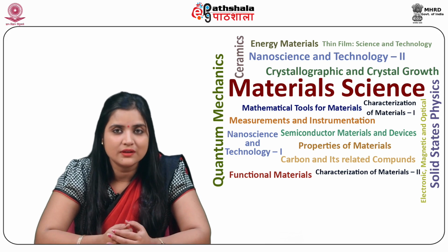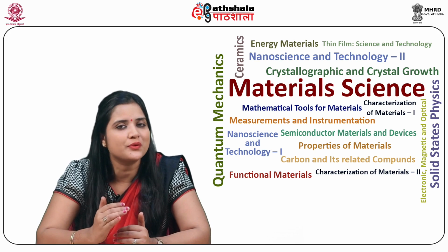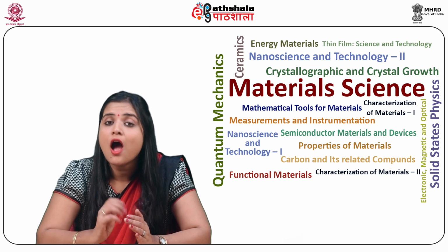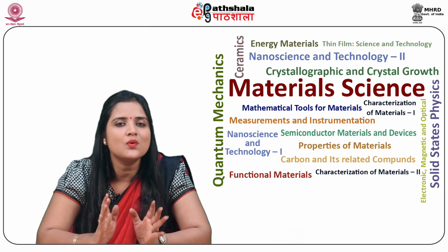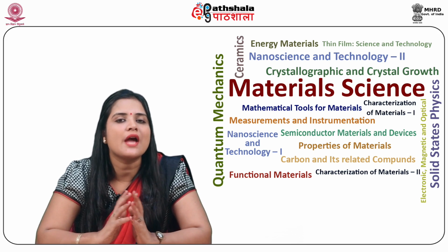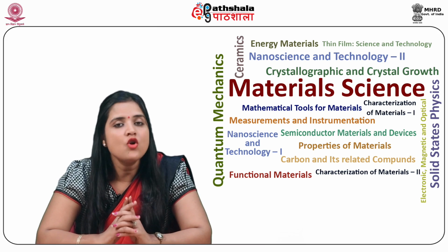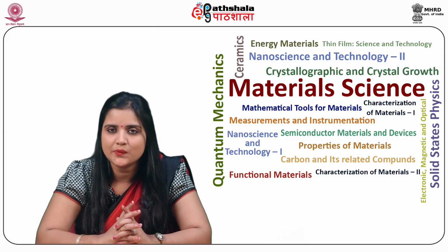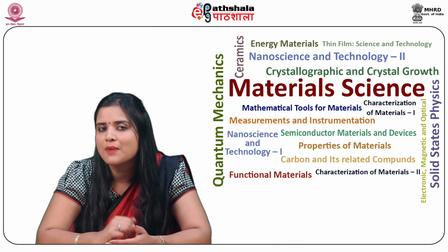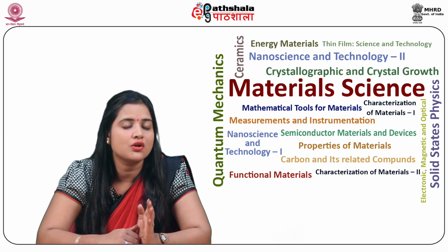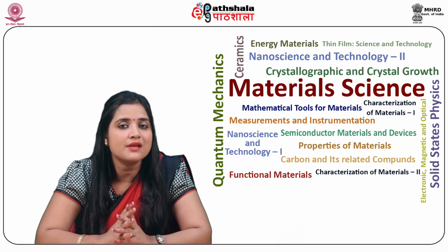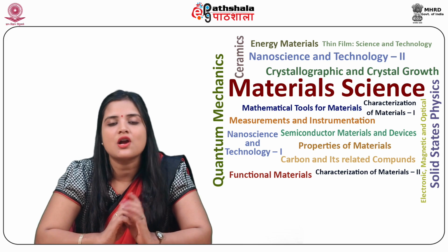Filters are the electrical circuits that allow a specific band of frequencies to pass through it without any attenuation. That is, output is approximately equal to the input, and it attenuates other frequencies which are lying outside the band. That is, output is nearly zero for those frequencies. Thus, all the filters have at least one pass band and one attenuation band, which can also be known as stop band. The frequencies that separate the pass and attenuation bands are called cutoff frequencies.